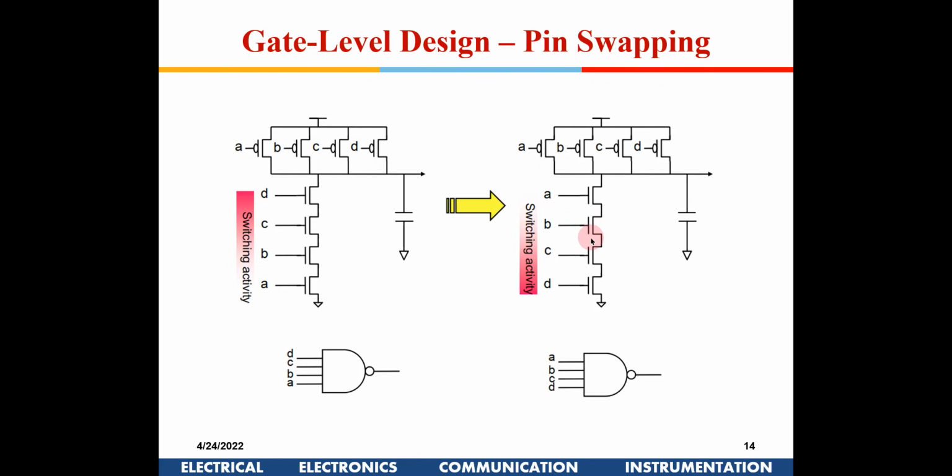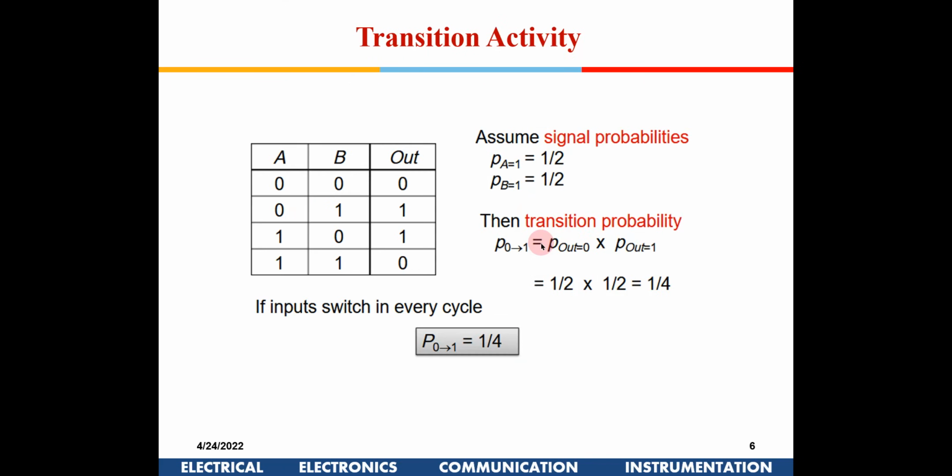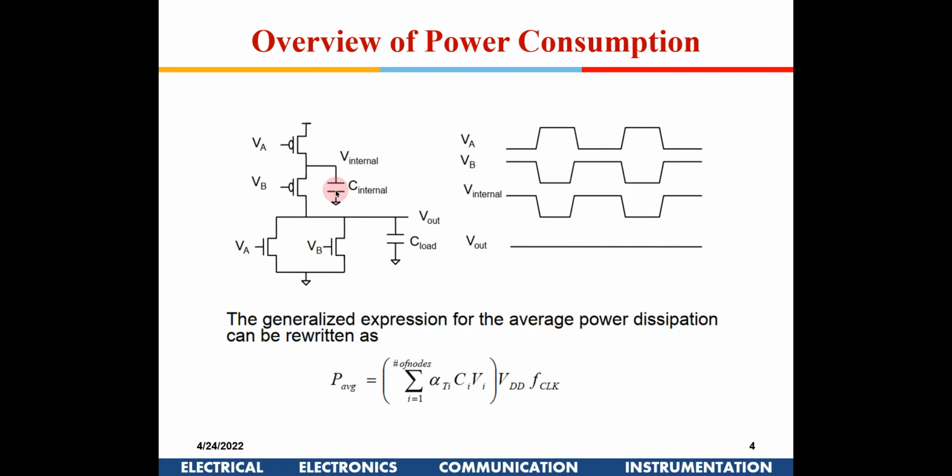For the PMOS circuit also we can, if I go back to my previous slide out here, if you see here, this is a NOR circuit, so in this particular circuit, the one which has got the least activity cycle should be placed here, right, because this output node should be charged to 1 when both are on, right?